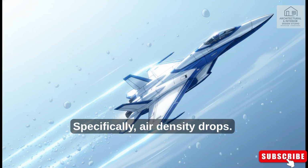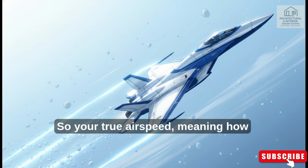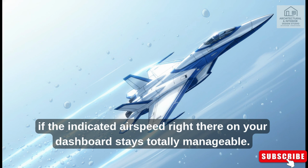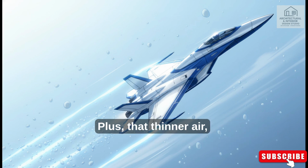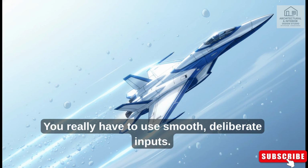Now, as you climb up to your cruise altitude, the physical environment changes. Specifically, air density drops. The air literally gets thinner, which means there's less resistance. So your true airspeed, meaning how fast you are actually moving across the physical map, goes up, even if the indicated airspeed right there on your dashboard stays totally manageable. Plus, that thinner air totally changes how your control surfaces feel in your hands. You really have to use smooth, deliberate inputs.